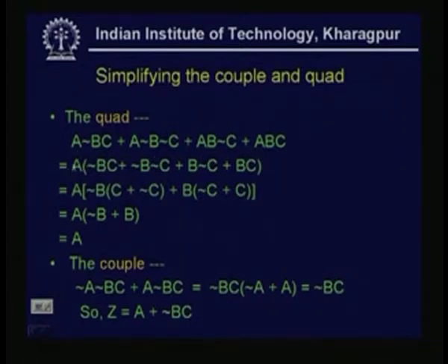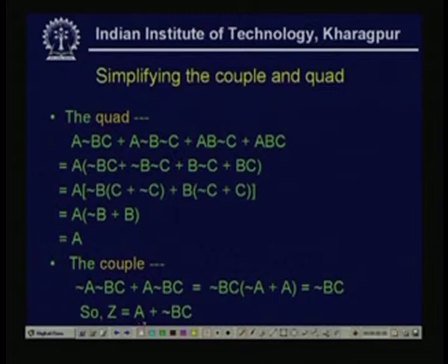From here, we notice that each of the min terms contains the literal A. So, I take A common, then the term will be A times B bar C, B bar C bar, B C bar, B C. Now, from the inner expression, if we consider the first 2 min terms, then B bar is common, and we take C plus C bar.